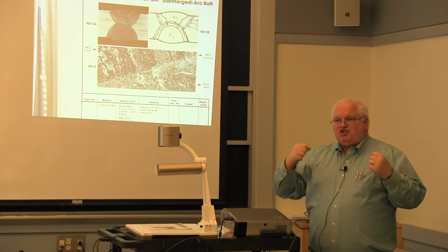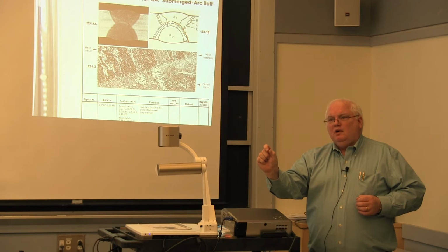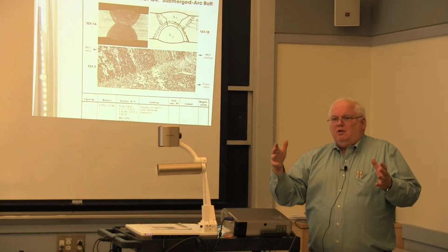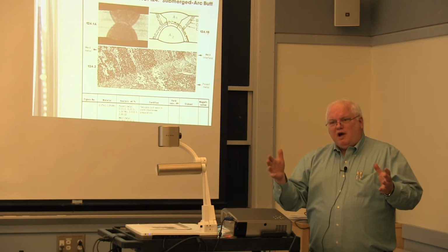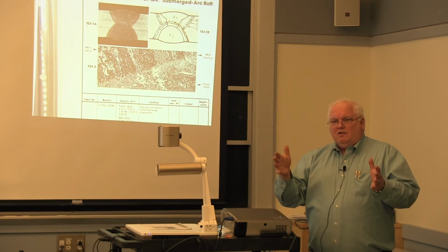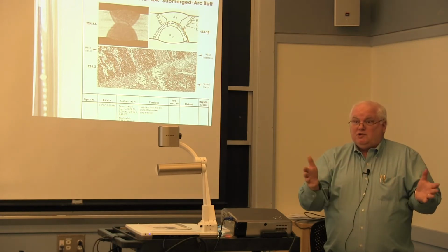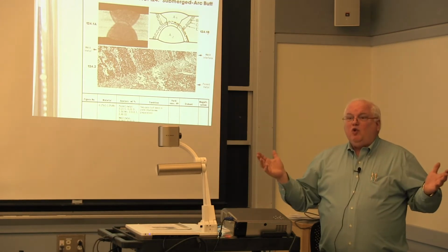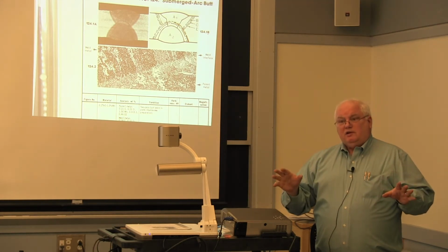That means all the strain in your structure is concentrated right on that weld. Even though your structure may only undergo 1% strain, if the weld metal is only 5% of your overall structure, that 1% gets multiplied by a factor of 20, because it's only 5% of the structure, and all of a sudden I got 20% strain in that weld. And the weld is overstrained.